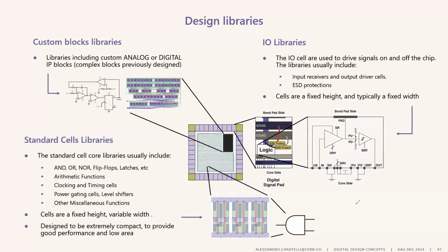In an ASIC, you can basically do anything. It's like having a whiteboard where you can start to draw from scratch. You don't have dots that you can connect. So all the digital design and writing the Verilog or VHDL code is identical. The synthesis and implementation part is a bit different because in this case you need to place the physical cells that will be produced. I don't know if it's clear.